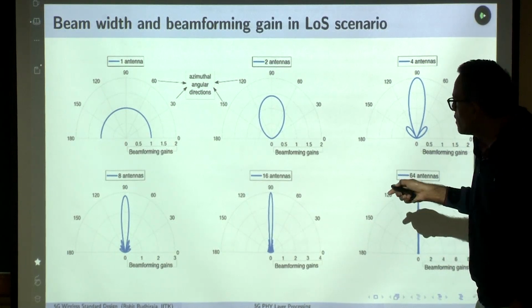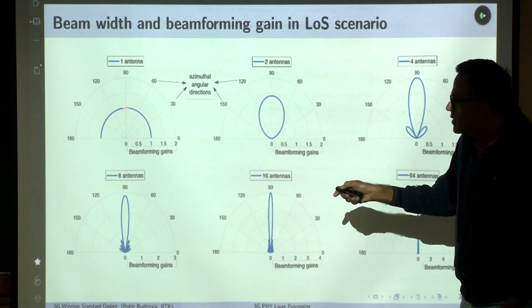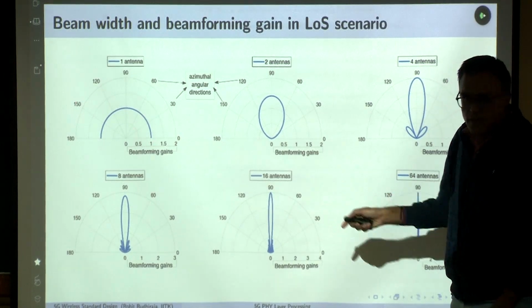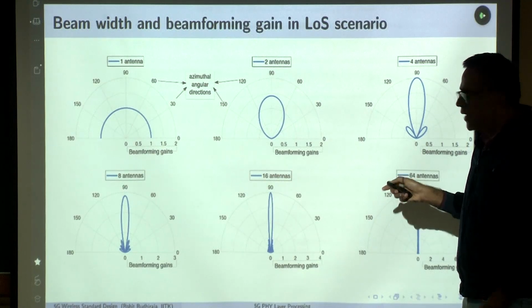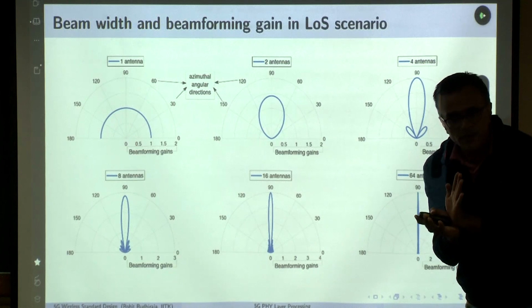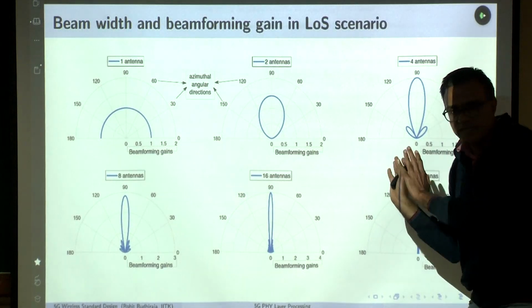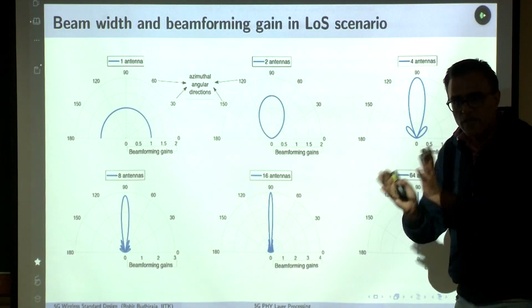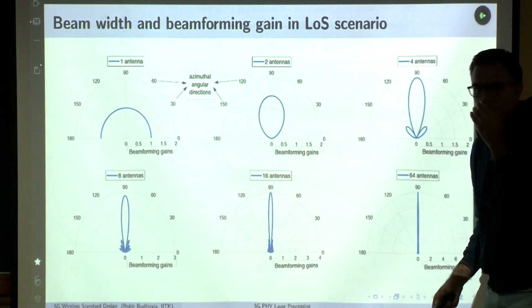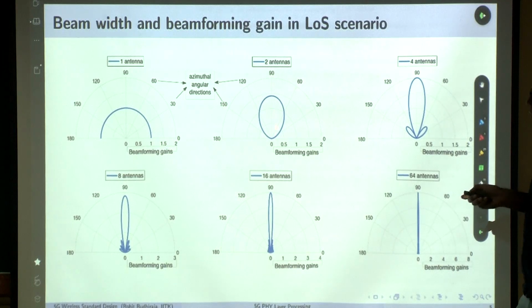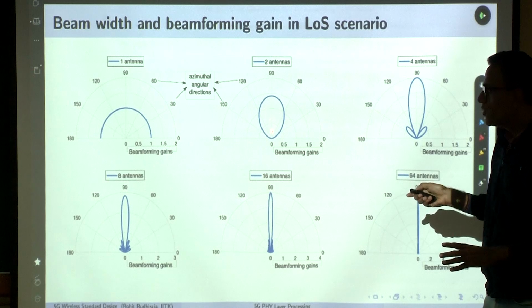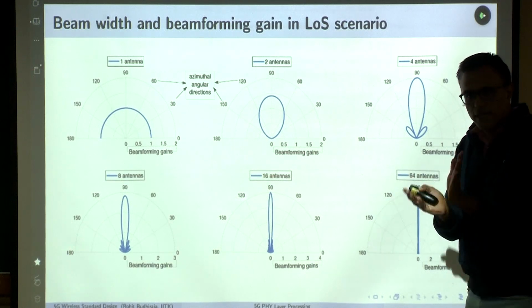With a two antenna system, and look at the gain is 1. This is the gain, that is what I have plotted. And I am talking about this picture only for a line of sight channel. For a non-line of sight channel, this picture does not hold, and we are talking about FR1 for line of sight implementation only.